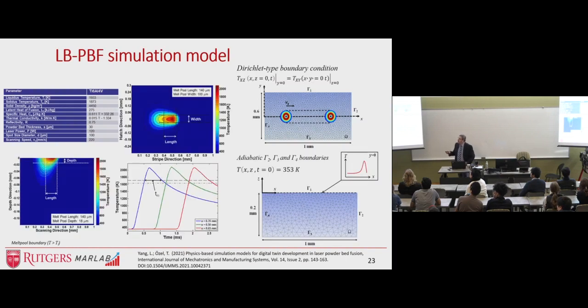the melt pool. This is only a thermal model. We can get its melt pool size and shape, and also the thermal profile, as well as the rise and fall of the temperatures and the locality, which means the time spent above the melting temperature, because that's the time that the heat may actually be transferred into convection and vaporization. It's a simple two-dimensional model that solves for the XY domain and then uses this solution to get the solution in the XZ domain.